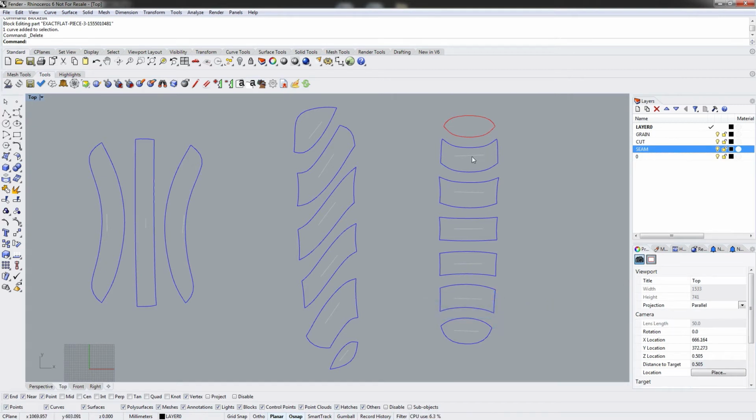So it's very easy to make these kinds of changes to your DXF, but most cutting table software does have the ability to turn off the grain line or do nothing with it. So you can either remove it in Rhino, or you can simply not import it in your cutting table software.